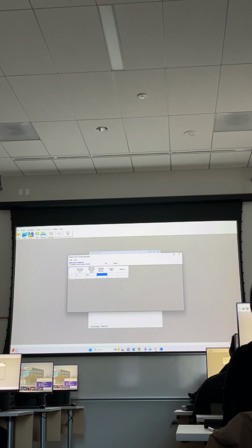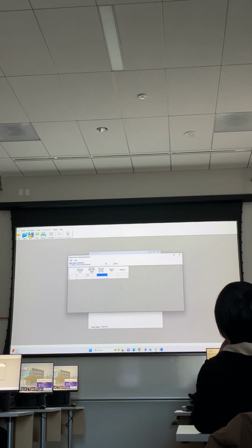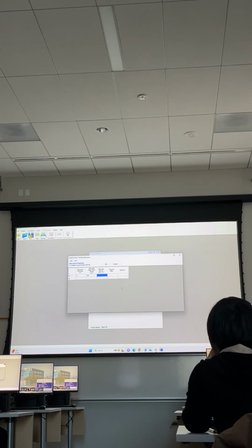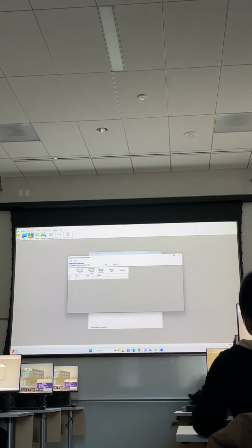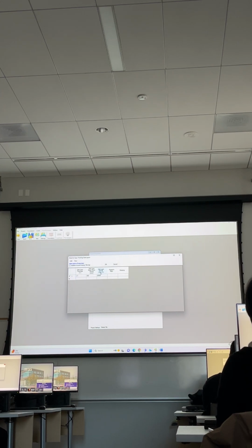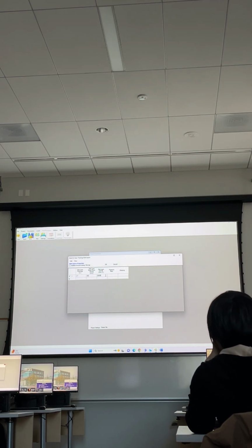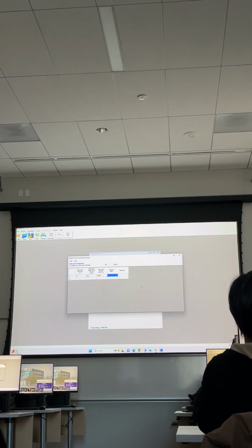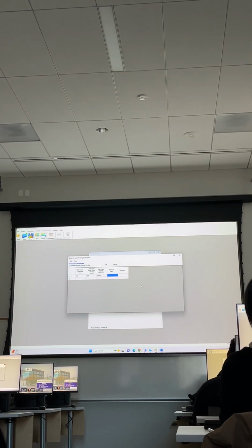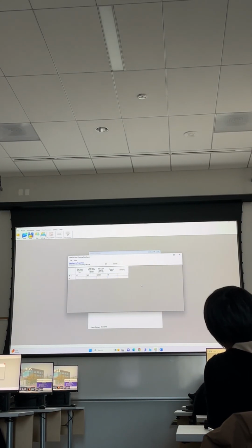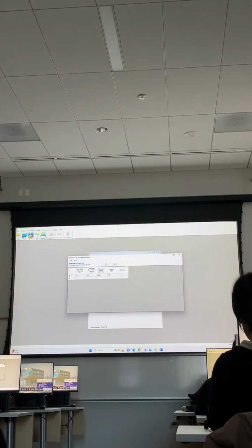Next one is the side layer unit weight. We can assume that the unit weight is 20,000 here because it's in newtons per cubic meter. Again, don't forget about the units and don't mess with that. It will end up with a very bad result. For the Poisson ratio, you can use the value 0.3, and for the damping, you can use the value 0.8.